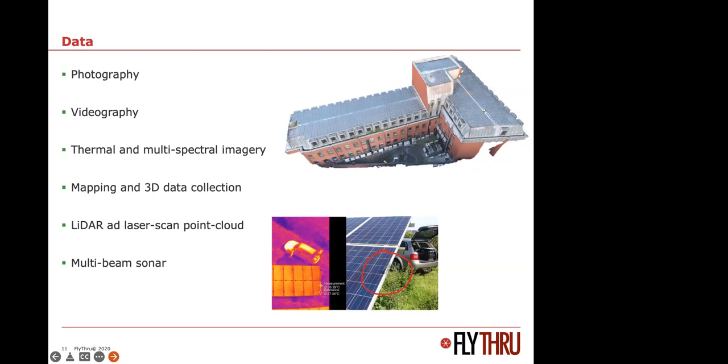It's measuring the intensity of return of light from a laser source, firing out between 700,000 and 1.4 million times per second in terms of the sensors that we carry. We also go underwater, so we carry multi-beam sonar as well, again creating that 3D picture from top to bottom.